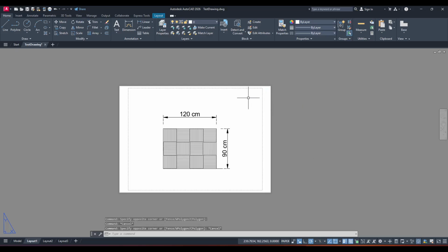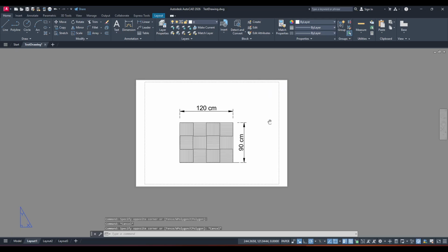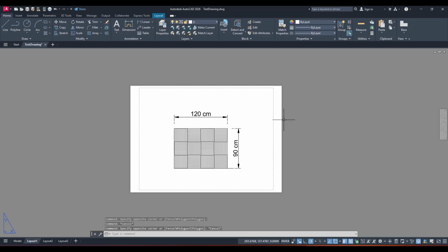If your layout is tight, or you prefer the keyboard, use the command approach. Simply type P space, or the shorter alias PS, and press enter. AutoCAD immediately switches you to paper space on the layout. This is especially handy if clicking is awkward or your viewport fills most of the sheet.